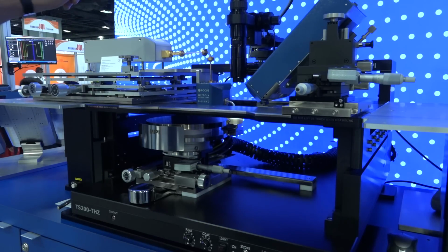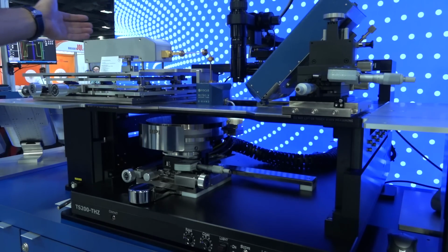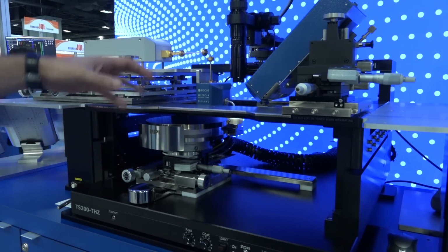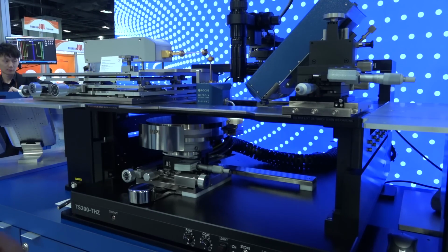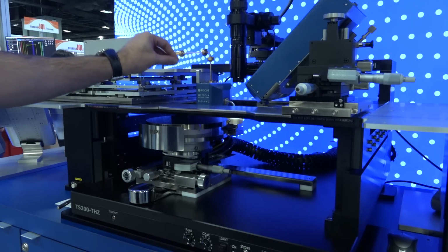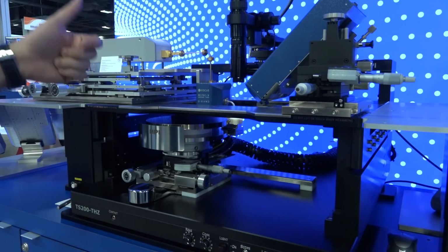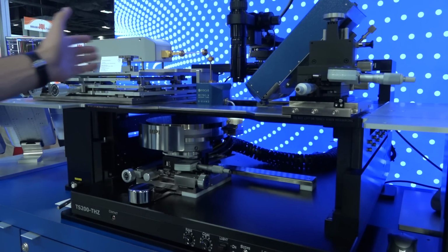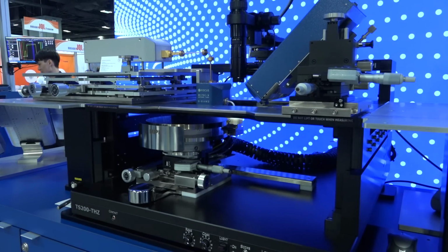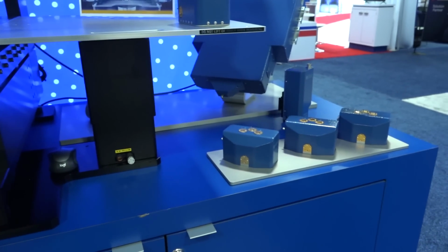We have the coupler access directly there. This particular example is connected to a Rohde & Schwarz head. But you can see that these probe stations from MPI are of course reconfigurable for any different band. Here at Focus, they want to make sure they give you all the tools ahead of time, so that when you do PA design, LNA design, and so on, you can actually characterize all that load pull at these very high frequencies, something that I see more and more of here on the booth, and there are a few other examples of it.